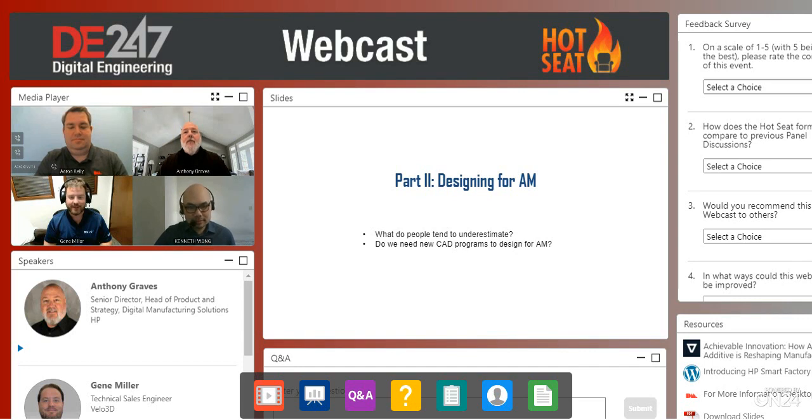If that were true, I wouldn't have a job, man. I would serve no purpose. There is no Staples easy button for this. You have to be educated. You have to know what will actually print. And that's education that Velo would help our customers with, so that when you are receiving a model, a design that an engineer has created, you need to look at it and say, I can print this overhang, but I can't print this one. I need to put support on this. And there are design considerations that you really need to take into account.